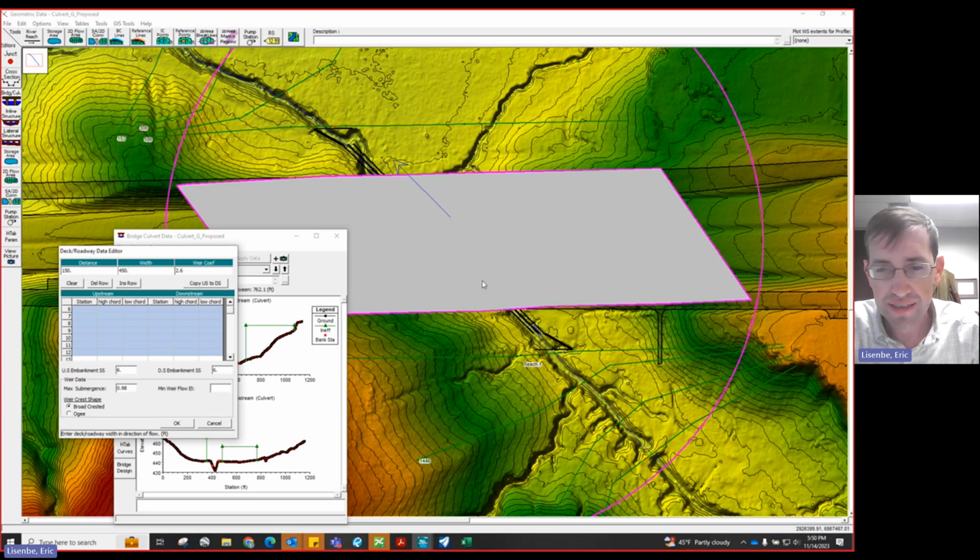I try to do that to make it line up. Again, this is why it's good to have the cross section immediately upstream, somewhat parallel to the roadway, to allow the bridge shape to closely match what it actually is. So I just tried to enter those in to make those match. The culvert length will be the actual culvert length that we have based on our culvert layout, and the flow lines that we actually have. But with that, I'll go ahead and get started.